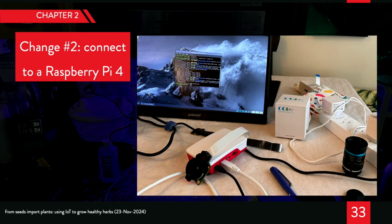And this also meant that I could connect the Pico W straight through to the Raspberry Pi and then remote desktop into the Pi and then start to control the Pico W remotely, using your standard Thonny IDE. So this actually started to become a pretty cool way to monitor things remotely, make sure that the software hadn't crashed or anything like that.